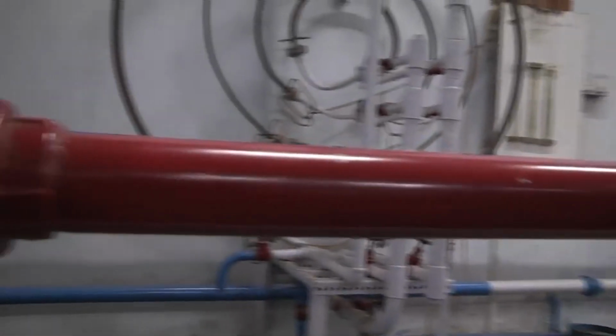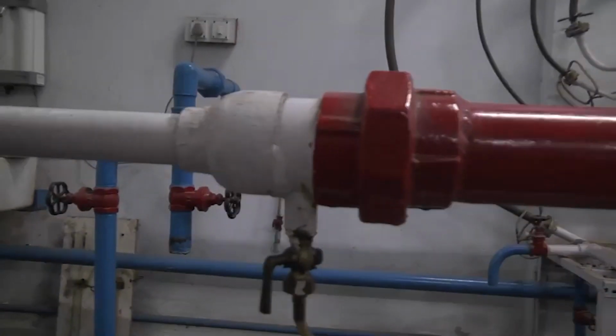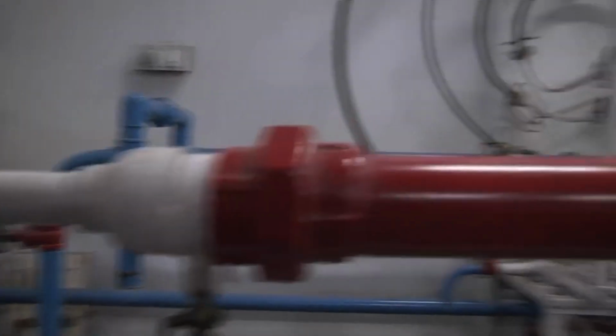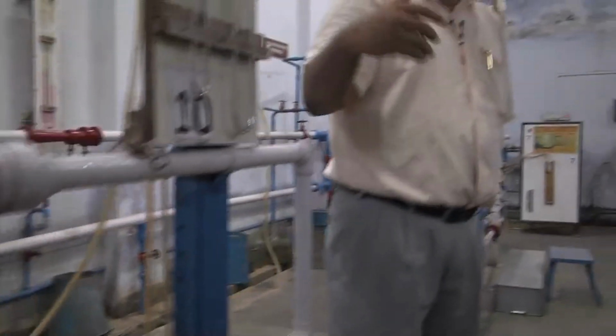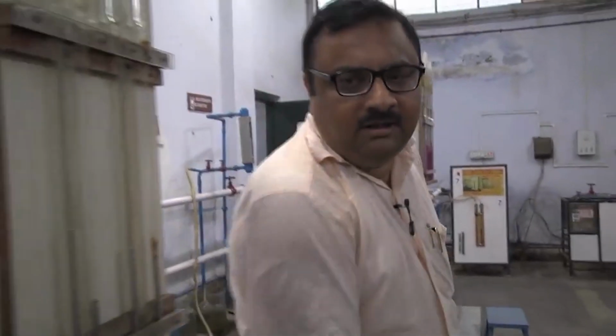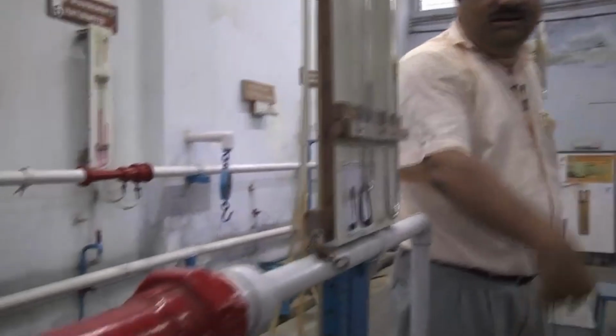So, this delta P is monitored using the manometer, the flow rate is measured from whatever liquid flow we get from the outlet, and then these two measurements are taken to compute the permeability of this porous medium. One can use Darcy's law, or other equations available for flow through porous media, to arrive at the flow resistance offered by the porous medium inside this red tube.